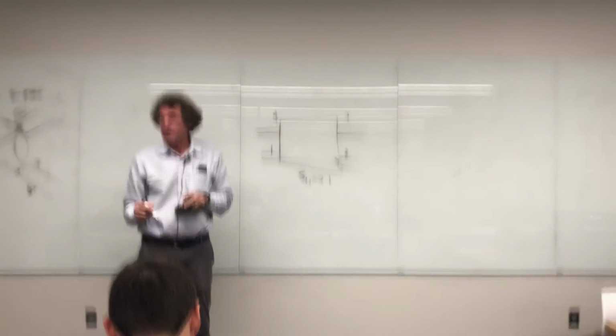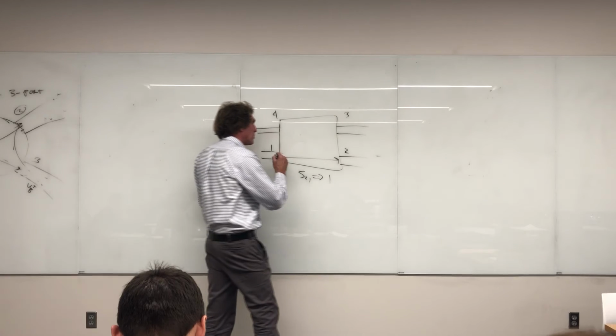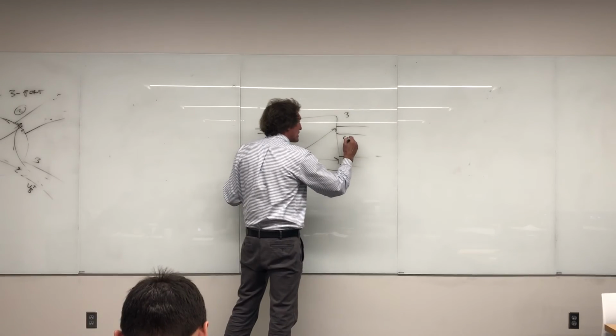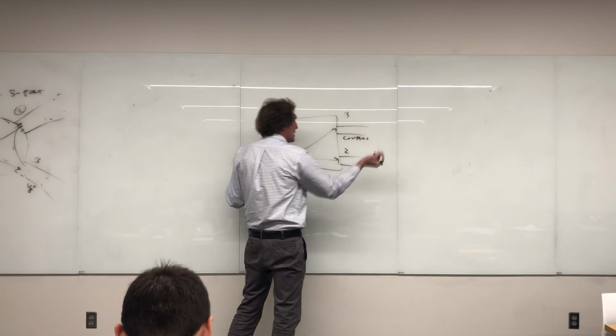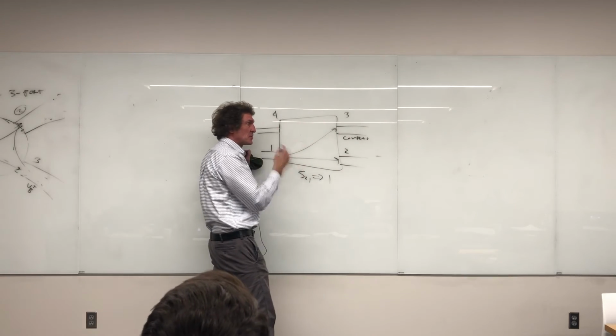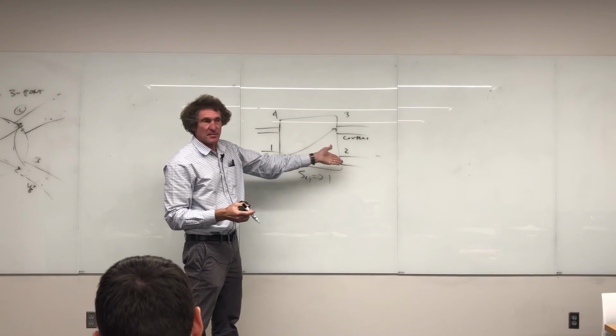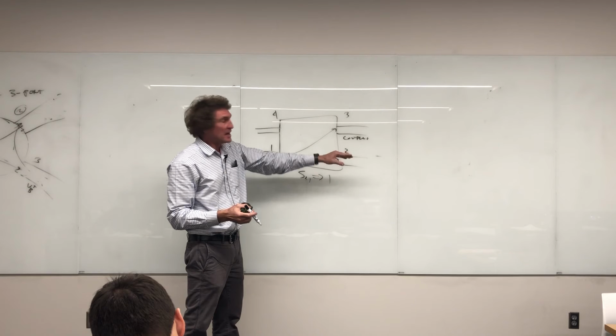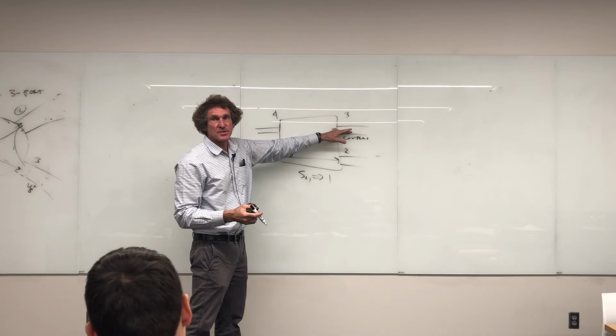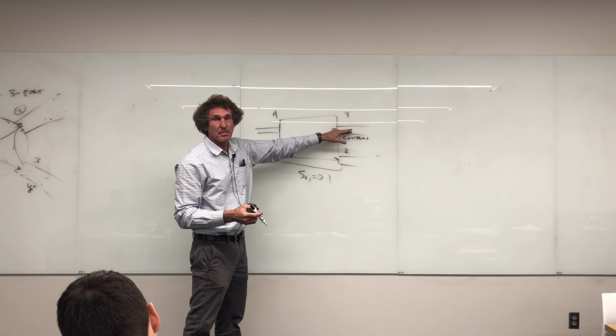Follow me on this, class? Now, there's a thing called a coupled port, too. He uses the word coupled. All right, and that's port 3. That's where you peel off some of the signal at the same time. It's going to be linked to an antenna for transmission. And that port right there will be used for signal processing information.